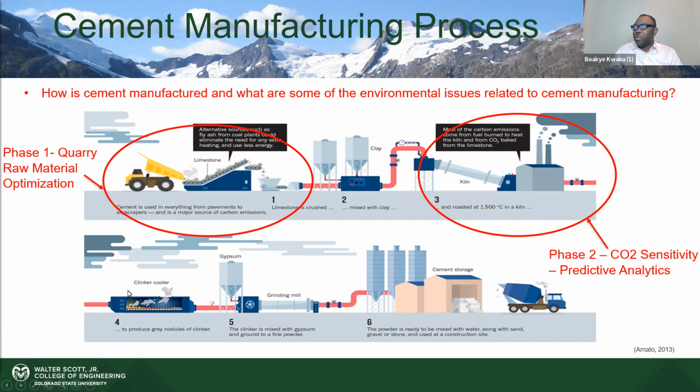The clinker is cooled down because of the amount of heat involved. When it is cooled down, we run it through a system called finish grinding. When the clinker comes out, it is in aggregate form, and therefore we have to powder it, to pulverize it. To pulverize it, we use either a finish mill, vertical mill, or a ball mill.